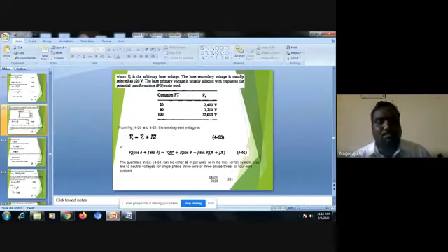Okay, so I am substituting the same Vs bar. Vs bar is equal to Vs at an angle of delta. When I expand that from polar to rectangular, Vs into cos delta plus j sin delta, I'll get, and Vr is the reference, Vr at an angle of 0 degrees, I'll get Vr only, plus I at an angle of minus theta.